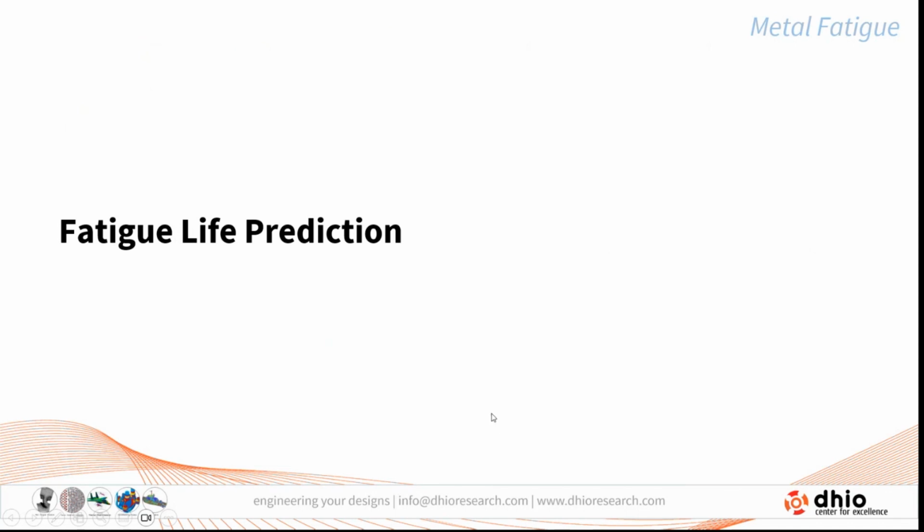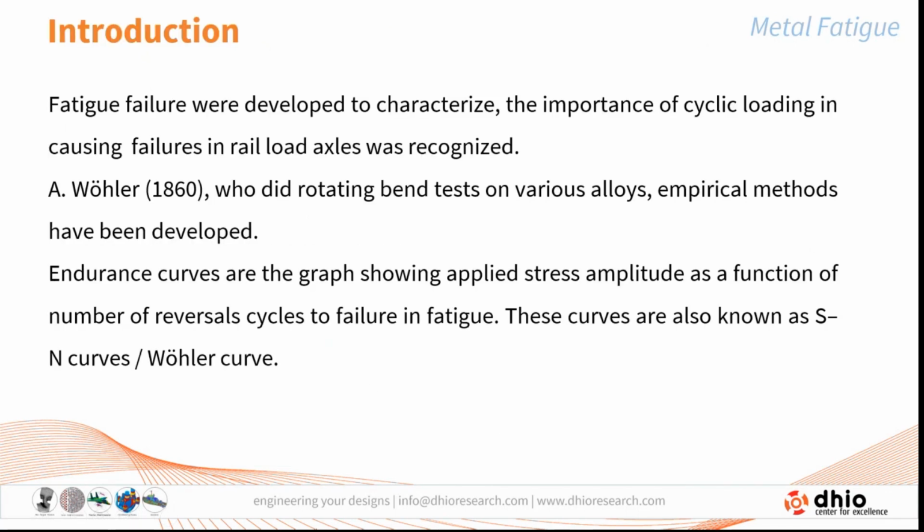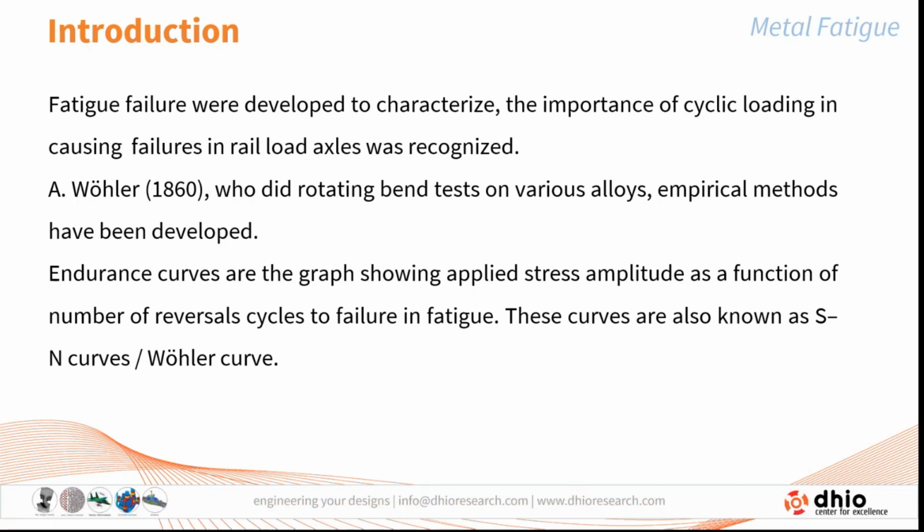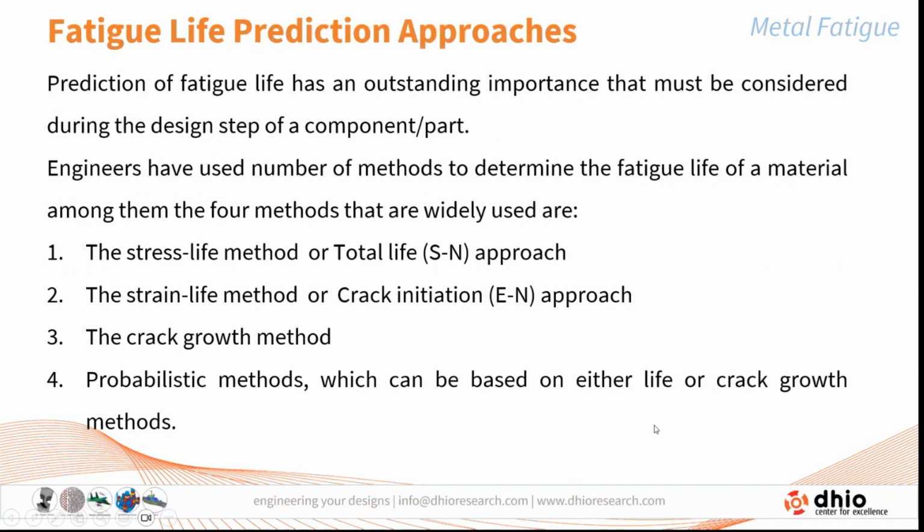Let us see how the fatigue life is going to be predicted. Fatigue failure theories were developed to characterize the importance of fatigue under cyclic loading, which was first observed by Wohler in rail wheel loads. He carried out an experiment, a rotating bending test on various alloys, and empirical relations were developed. That is what we call the endurance curve, also called the Wohler curve.